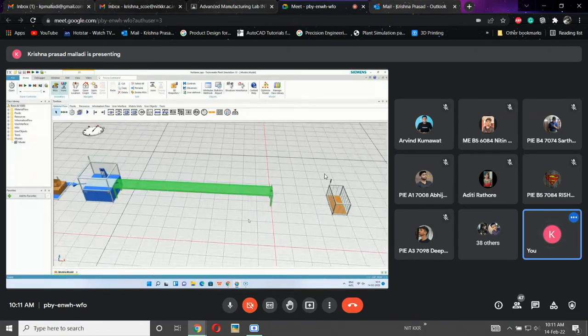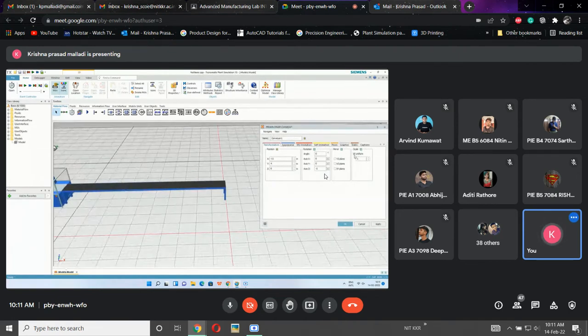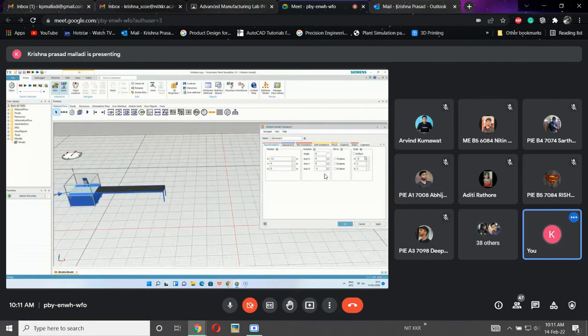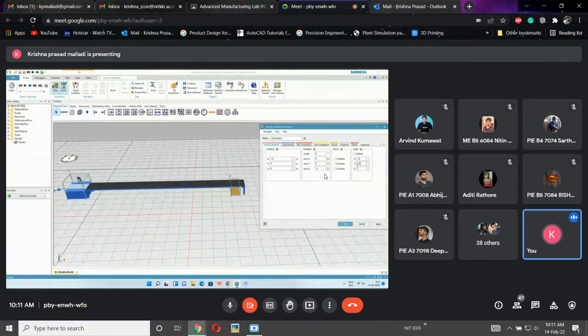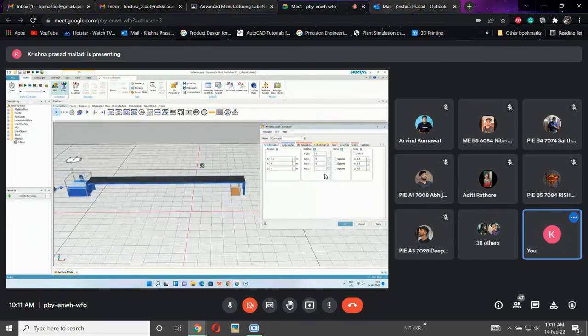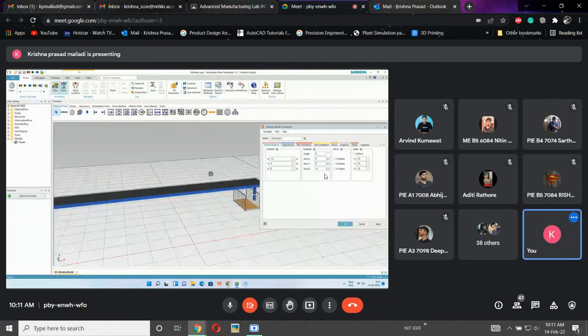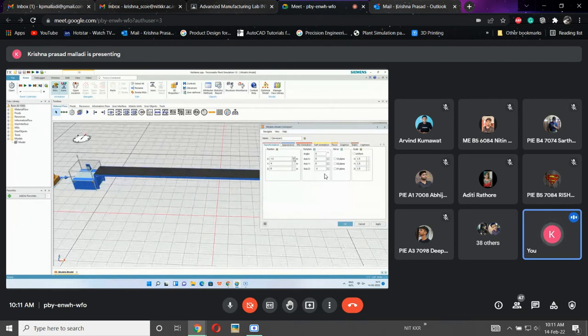See, whenever I click this M, there are these handles, and I can directly drag and drop here. But there is one more thing also. Right click and add 3D properties. Same X, Y, and Z, and there is an angle rotation. In that uniform, I can click this one in X. I want to increase its length, 1.5. I can increase this also 1.5, so this is also increased. If I alter the Z, height is also increased. Clear? This is how we are going to change the conveyor also in this manner.